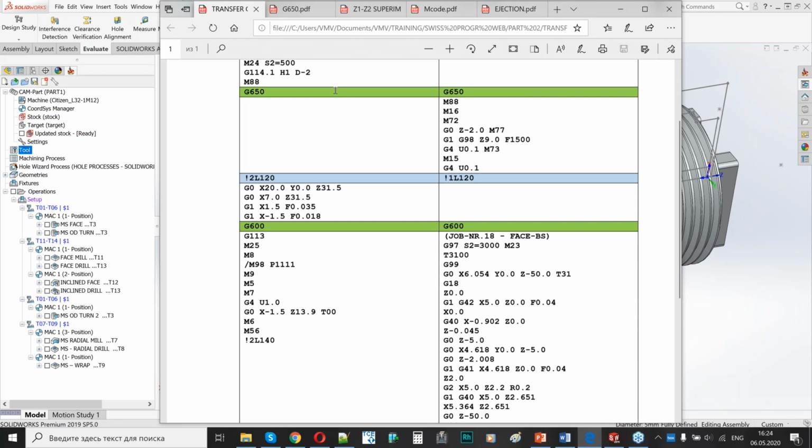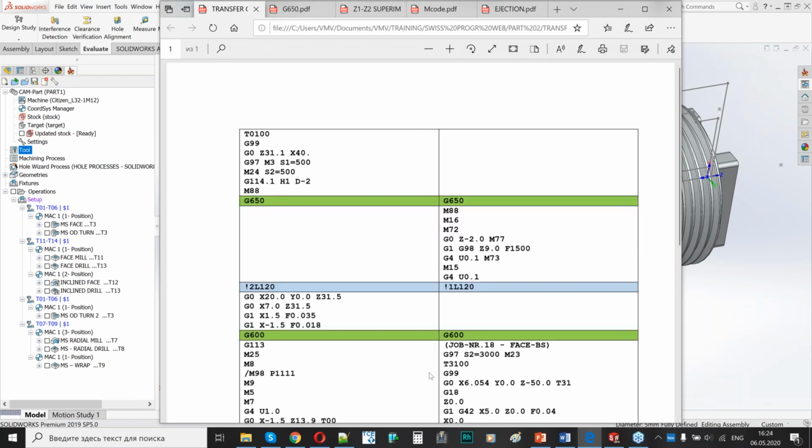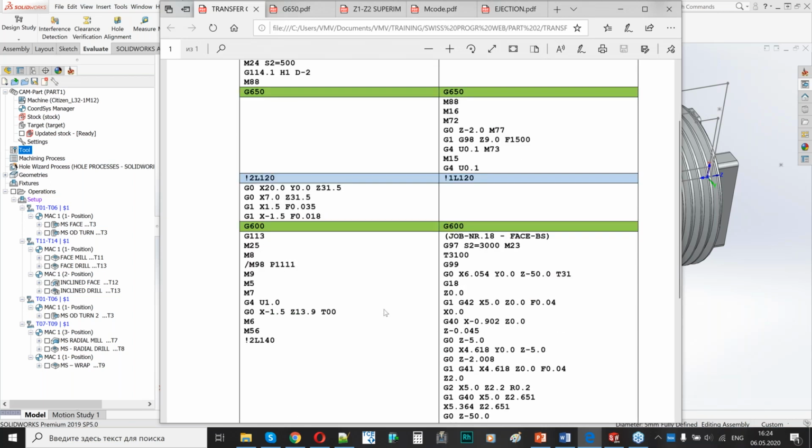And this code after part transfer for the machine means that spindle should go out from the main spindle with part to its reference position. So I should not add any codes here. Everything will be automatic, but it is better for the customer to know about this, because it's a little bit scary when you don't have G0 movement, but your back spindle will go with the part somewhere and you didn't program this. Okay, so this is several blocks which will be performed inside the software.